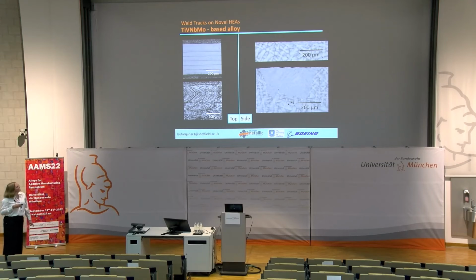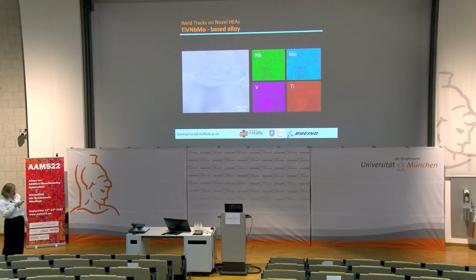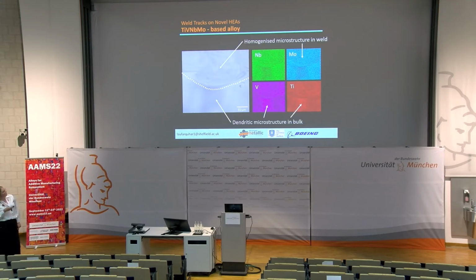We also had some very optimistic results. So here's an alloy which unfortunately I can't disclose the composition because it's of interest to my industrial sponsor. But you can see that there's no cracking observed at any volume energy density. And also, we have some EDX analysis, which here you can see the weld if you can't see it very well. And also, the welding has resulted in homogenization of the microstructure versus the arc-melted sample.